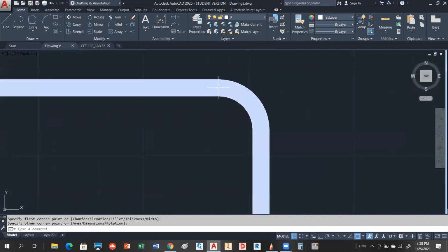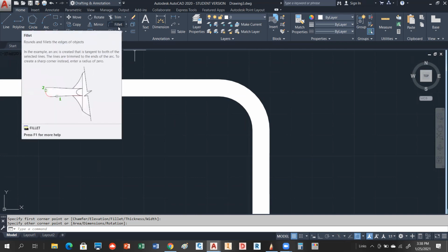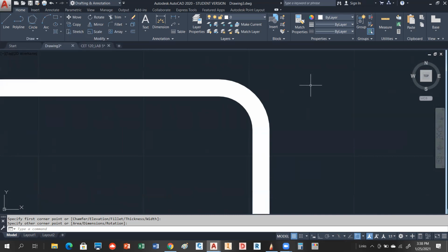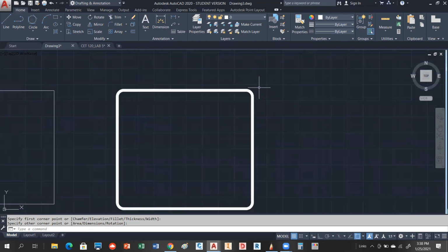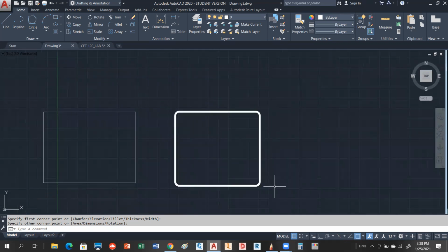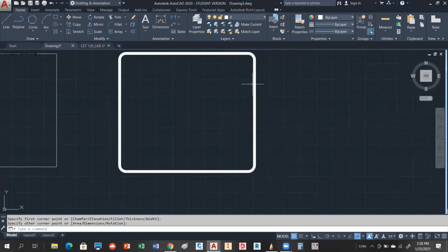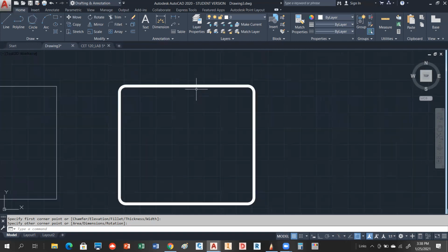And so this guy right here is called a fillet. And that's a very common property. In fact, there's a command up here called fillet, which we'll be talking about in a couple of weeks. So this one's used a lot when you do drafting and CAD work and that kind of stuff. But this has the built-in fillet. And the thing is that when you actually create this, the fillet will have the same radius value for each of the corners. Okay. So if I would explode this polyline, I'm going to get back 4 lines and 4 arcs. That's what it'll give me. Okay. Any questions?